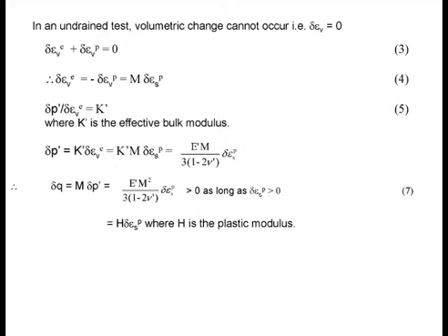And we know from generalized Hooke's law that as you compress the soil elastically, elastic volumetric strain occurs, and the mean effective stress has to increase. You have to increase the mean effective stress to compress the soil, right? And what is the rate of increase? Very simple. The rate of increase of mean effective stress with elastic volumetric strain is given by the effective bulk modulus of the soil skeleton. The bulk modulus of the soil skeleton. Now, when you work that out, you realize that this is positive.